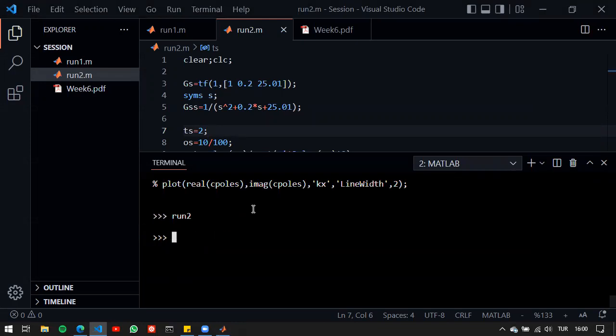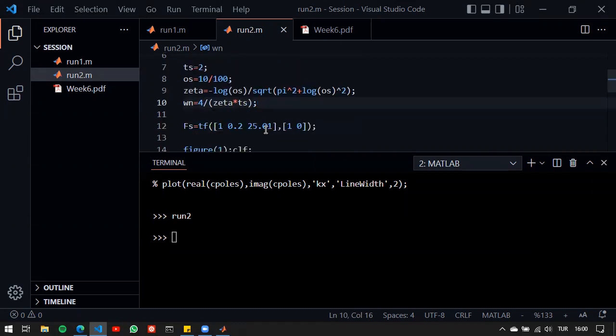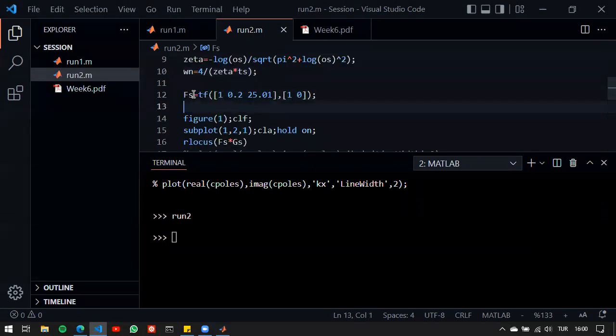If you simplify this, you will see that this is k divided by s plus k, because I have just s and nothing else. So the gain that I choose is also the pole on the real axis here. Therefore, I'm looking for 2, because if zeta is equal to 1, then 4 divided by 2 gives us 2. Therefore, I need to choose gain 2 here.